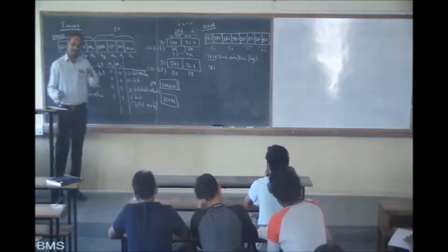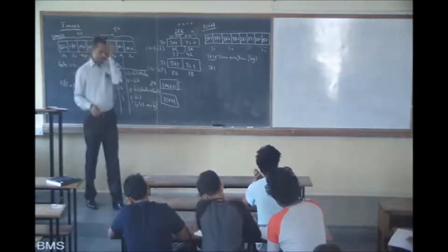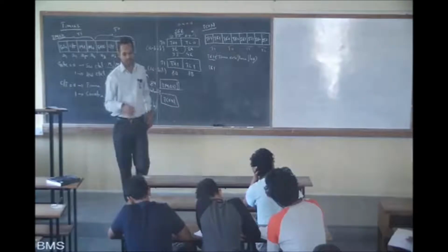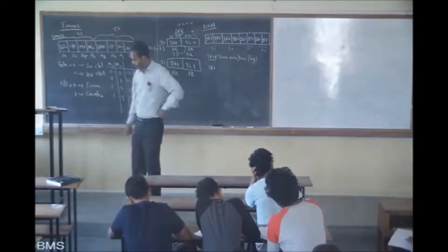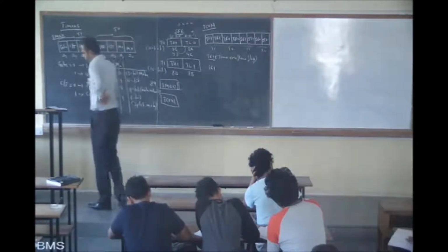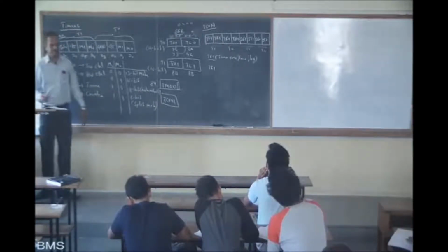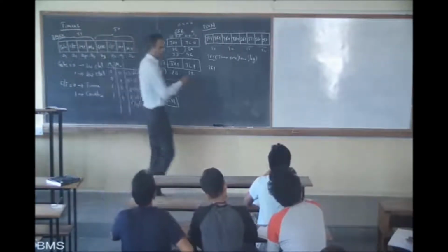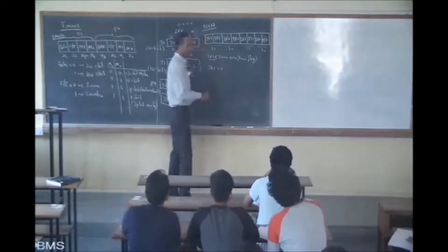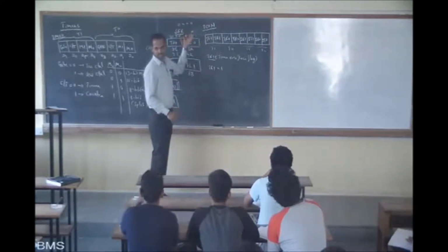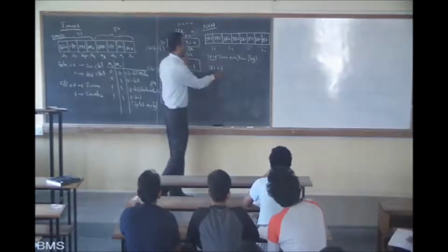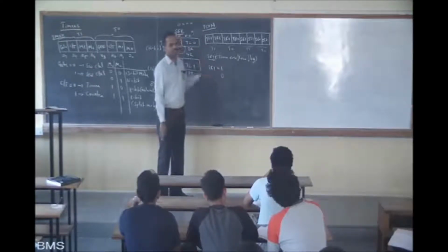Written. Set and cleared by software. You have to set it by software, clear it by software. What is this timer start bit? When you set it as 1, then this counting starts. When you set it as 0, counting stops.